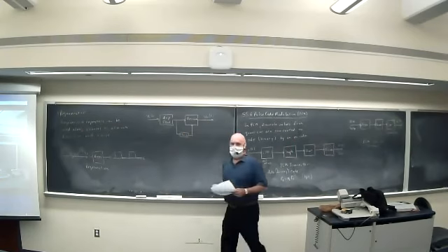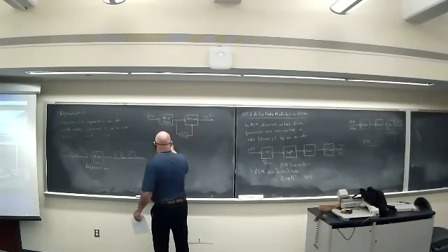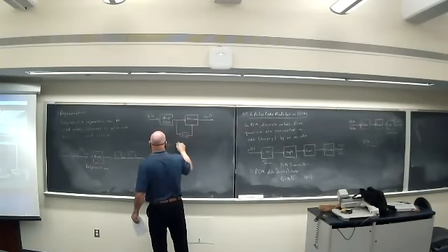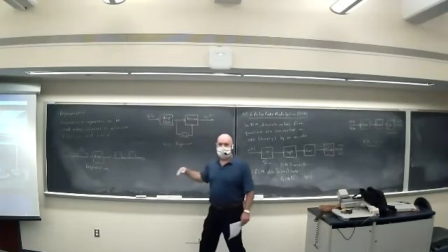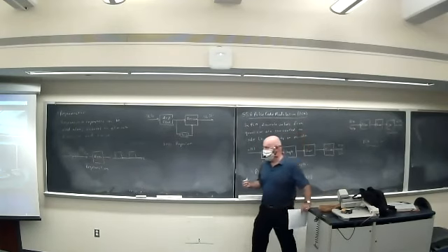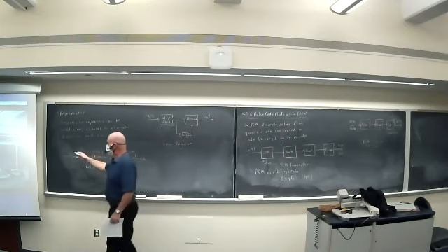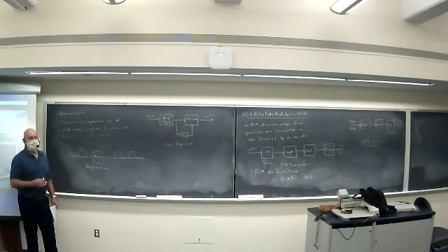But here, I'm just making this decision at any point about whether the pulse is a 0 or a 1. So I really just recreate the binary pattern and then recreate the digital waveform. It's not any sort of filtering of this thing to create the output. It's actually making this decision at each sample instant about whether it's a 0 or 1, and then regenerating the waveform.